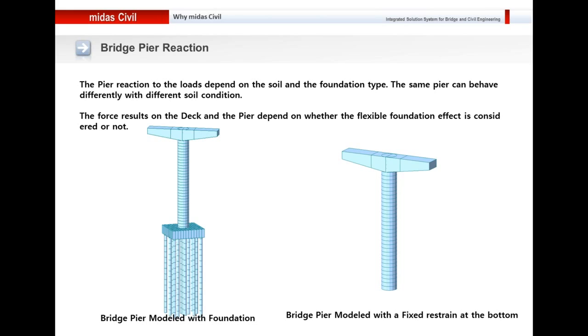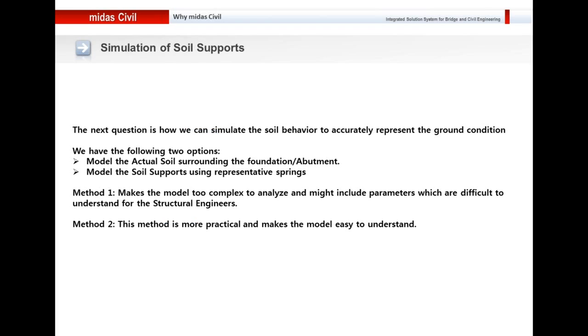But the results can be substantially different if you model the support beneath the pier. And once again, if you have different types of soils, the results that you obtain for the design or the deflection can be substantially different. I have done a comparison between different types of soil, and I'm going to share that comparison with you later on.